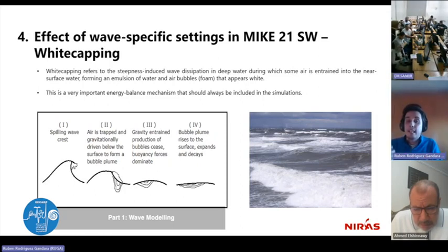And now the thing is that you will have to justify with offshore measurements or whatever that by modifying that coefficient of white capping, you get what the measurements say. Only in that case can you start playing with that coefficient and give it a physical sense. Otherwise, I would leave the default value, but for sure you need to activate white capping.